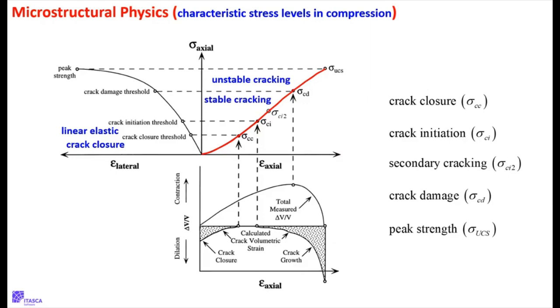Now, from that data, you can compute what we call the volumetric strain, change in volume over volume. The volumetric strain we can show is essentially the sum of the strain in 1, strain in 2, and strain in 3, X, Y, Z. For this case, those are just axial and then two bulging out in the cylinder, and the bulging out strains are the same.